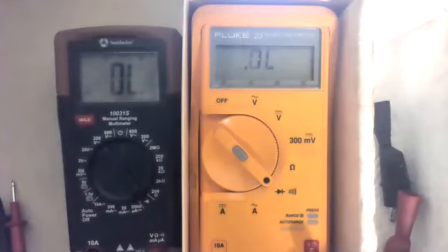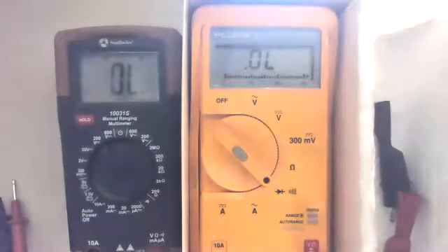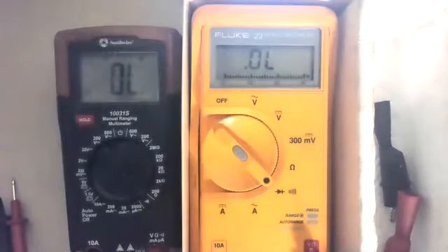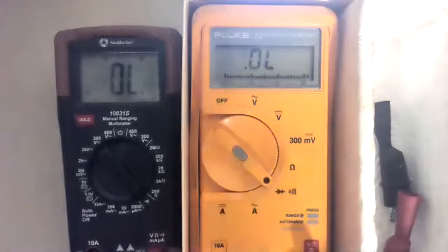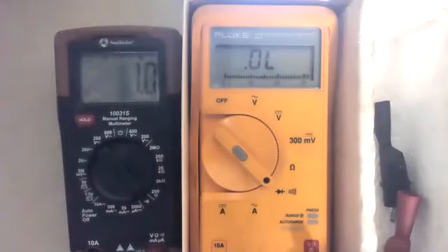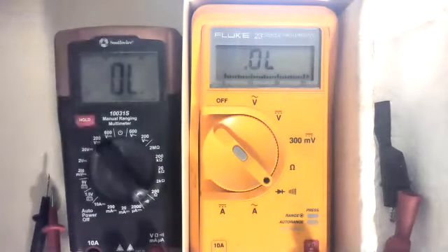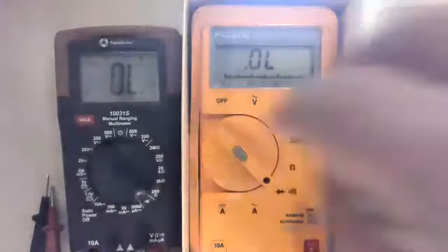Now, if it's all the way open like that, you won't make a noise. Yeah, there we go. We have no resistance there. If you have a lot of resistance, depending on the meter, it may not make the noise. It might just do a beep really quick and then give you a value. But if it's 0, this is a cheaper meter, it's going to tell you that you have a complete circuit. You have continuity when it starts making that noise.